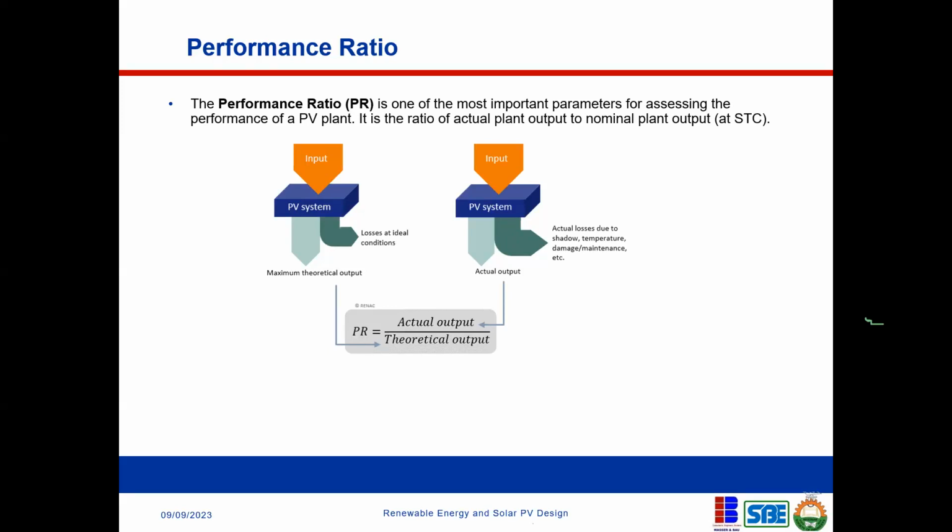So it's rated in percentage. So if I have a PV module and, after installation, I take my measurements of what it's producing, to compare to what it should have given me under standard test condition, I can now come and say, oh, this PV panel is performing at 75 performance ratio. What that means is that 25% of what I should have gotten at standard test condition is eroded. So that is minus 25. So its performance ratio is 75.